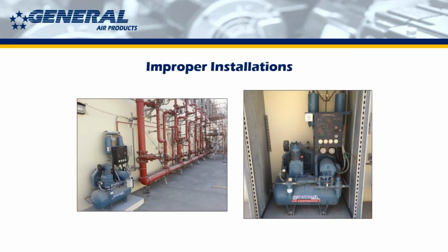You want to make sure that you have open airflow around this. These are both good pictures of bad installations. This one outside is completely open and outside. I believe this was over in the Middle East, actually. So they weren't really thinking about rain or anything like that. But that said, none of our compressors are meant to get wet. They will break. So they do have to have some sort of housing around them.